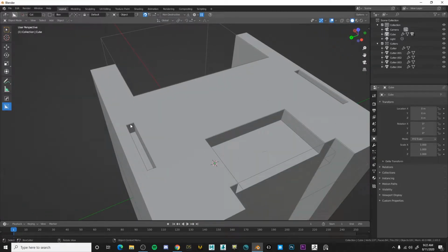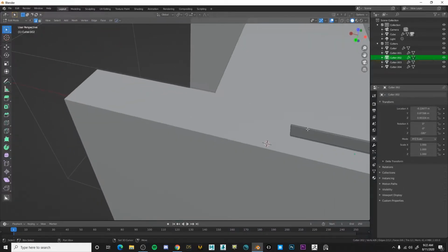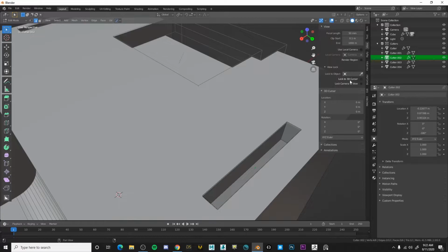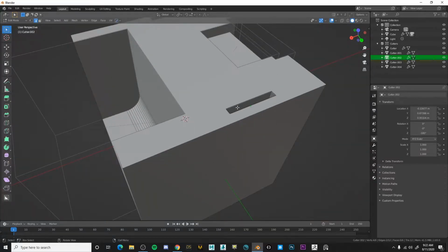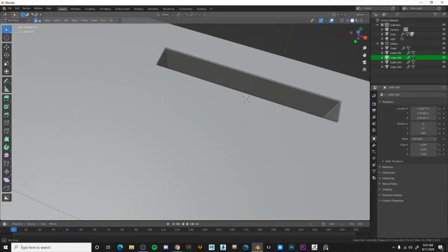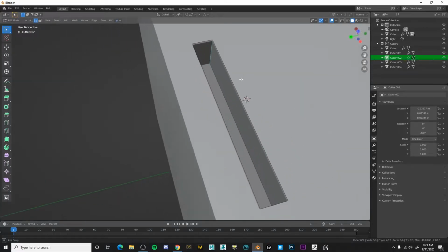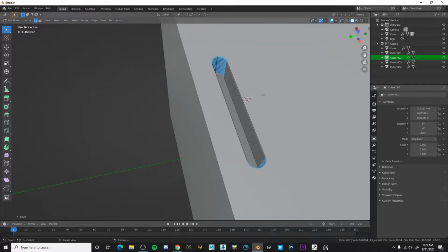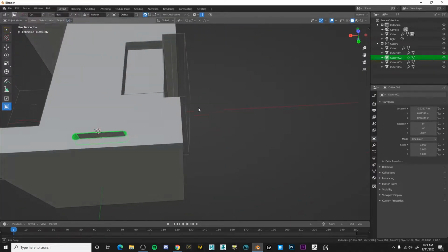Let's say I want to edit all of these. So I'm just gonna go to these and settings, select these. That's okay. So let me just turn on the view lock to 3D cursor, so I can just rotate around the 3D cursor. Shift right click to put the cursor wherever you want to rotate from. So yeah, let's select the edges, and now I want to add bevel to it. So Control B, then yep, this is done. And now go back to the object mode.